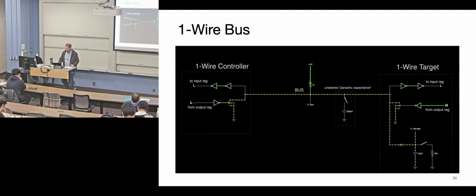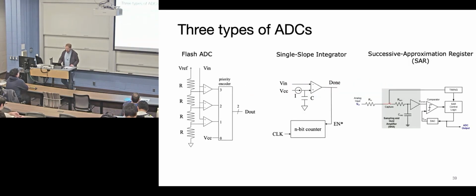All right, let's go quickly through ADCs. We just covered it. I don't know if we have to spend that much time on it, but it's important to know the difference between the three types of ADCs. Really, it's about knowing the trade-offs about why one's better than another one. So flash ADCs, as the name suggests, is the fastest. Those values are always immediately available at the rate of your comparators, so less than 1 clock cycle.